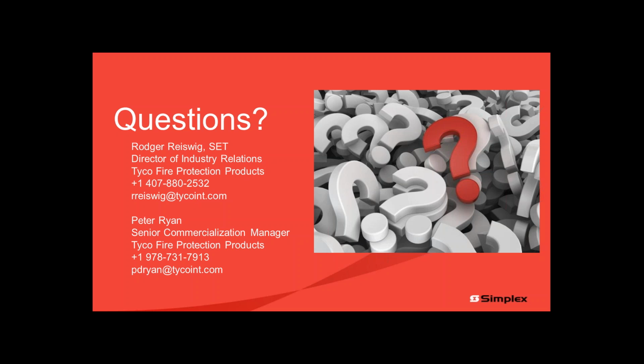The follow-up question was about the XAD that we've mentioned a few times. Could you provide some commentary on the design of the pipe, how you would use it in an open area like a factory where you're doing point sampling instead of having it in an actual duct? Yeah, for the Bethesda system or Xtralis, they have programs that you need to really utilize, and you put in how large the area of your room is, how high the ceiling is, the type of environment that you have, and what you're looking to sample for, meaning how much smoke you want to know about before it goes into alarm. And all of that goes into a program. They call it the Aspire program.